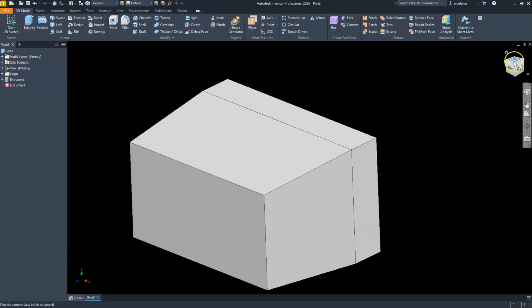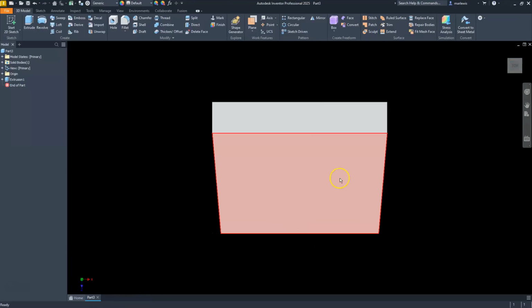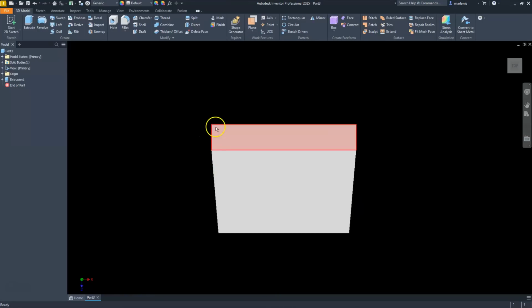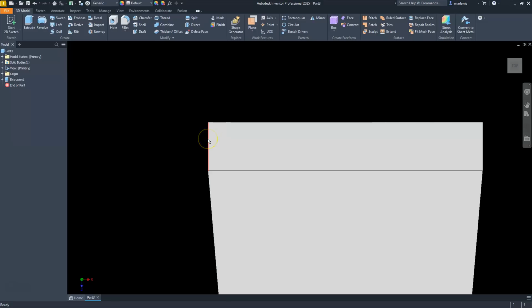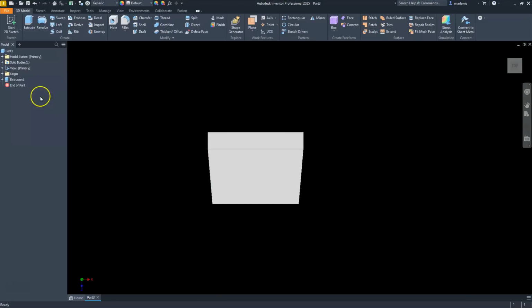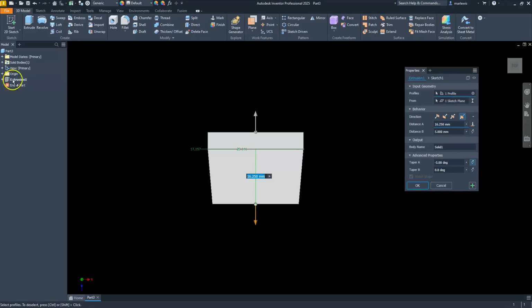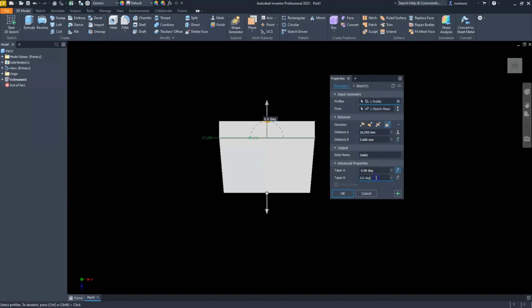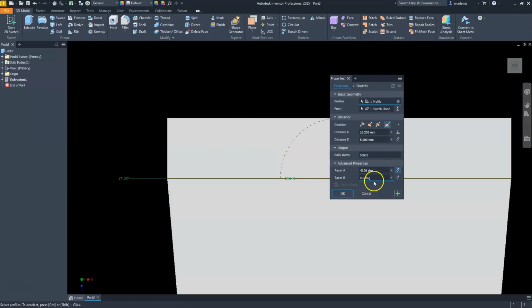And you're going to see that if I take a look at this on the top view, I do have a part going here, going down 5 degrees. And I don't know if I put that taper on the top half. It looks like it's actually straight, but I can come back and manipulate this. I'm just going to double click on this. And you can see that that's one of the huge benefits. You can see now that in this window, I did not put a taper on the second one, right? So that's one of those things I can go back and manipulate if I make a mistake. So if I make that 5 and send it inward, there we go.